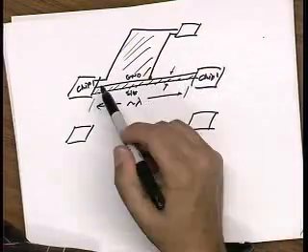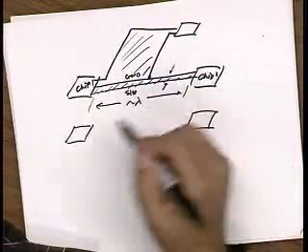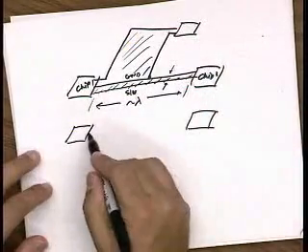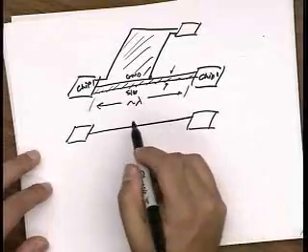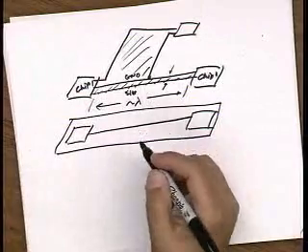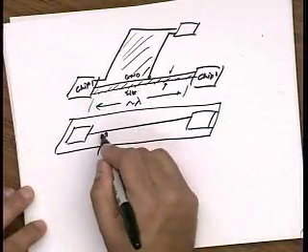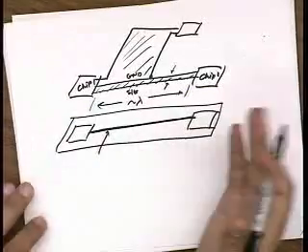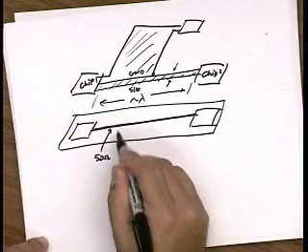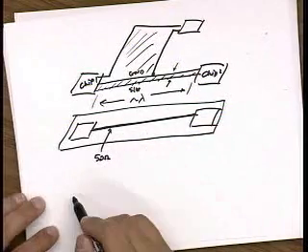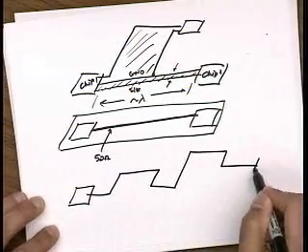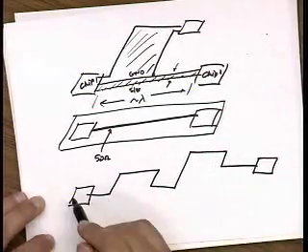On the other hand, if I match these lines, the reflections go away and everything is nice. And the nice thing about using a microstrip transmission line is that it's a very well-defined impedance. So I can tell the board manufacturer to make the width of this wire just right to get 50 ohms or 75 ohms or 200 ohms, whatever I need. And that will form a transmission line with my ground plane. And no matter how I route that, I don't even have to worry about what it looks like. Just automatically,